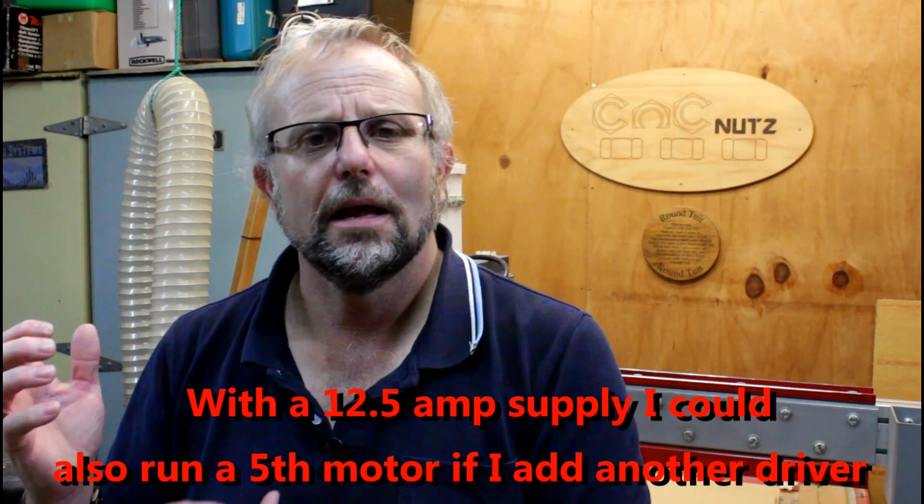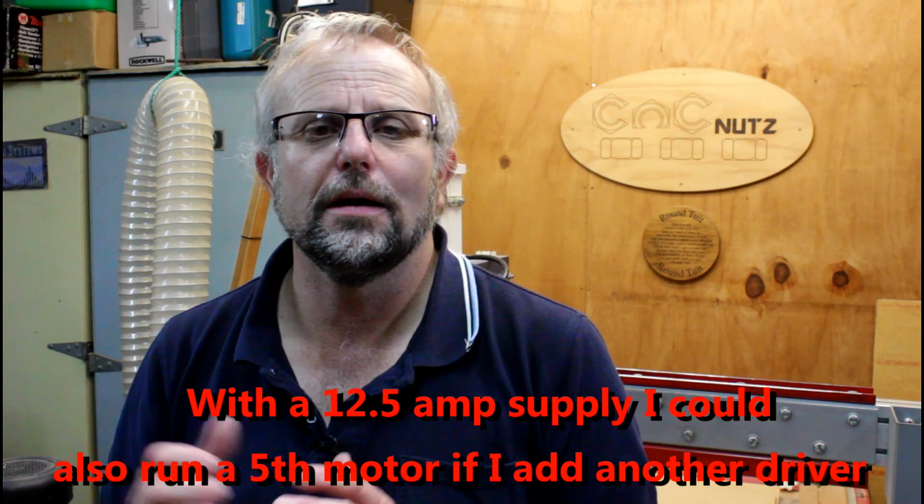So when it comes to choosing a power supply, I'd have a choice of a 48 volt 10 amp power supply or a 48 volt 12.5. And personally, I'd go for the 12.5. I don't like the idea of running a power supply close to its upper limit. So in this particular instance, the 12.5 would have that little bit of extra headroom and less stress on its components, because its components are rated to supply even more current. Whereas the 10 amp one, you're going to be running it close to its maximum and they're only rated for 10 amps. So personally, I'd go for the 12.5, though many Gecko kits are sold with a 48 volt 10 amp power supply and they run perfectly well.